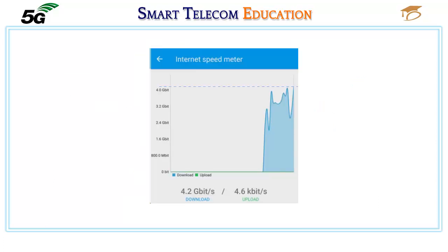Peak data rate is the maximum achievable data rate under ideal conditions, in bits per second, which is the received data bits assuming error-free conditions assignable to a single mobile station, when all assignable radio resources for the corresponding link direction are utilized, that is excluding radio resources that are used for physical layer synchronization, reference signals or pilots, guard bands and guard times. Peak data rate is defined for a single mobile station.